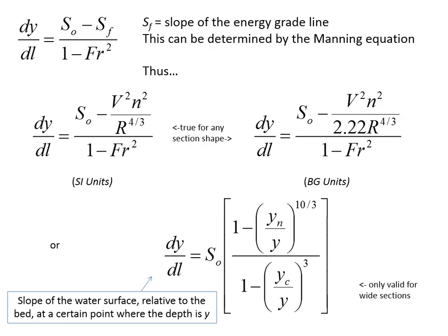So we calculated that, and the normal depth was above that. When we calculated the normal depth, we found that there was some normal depth of 0.912 meters. And then the actual water depth at the location we were interested in, maybe this was our location of interest, Y was 2.0 meters right here.